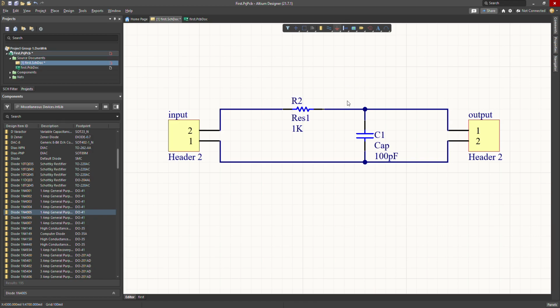And to make a power port, as Altium calls it, we are going to start with a ground power port. Let's say I want to ground this line here. I want to ground this wire and define that the name of this wire is ground, and this is the ground side of the circuit. So I'm just going to bring the ground here and connect it to the design, or we can connect it here. Now that's basically telling Altium this is the ground name, or the wire name is ground.